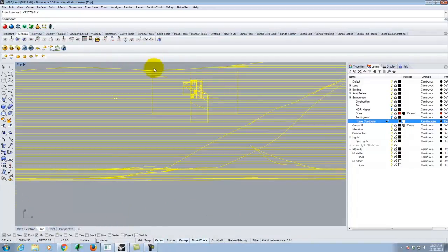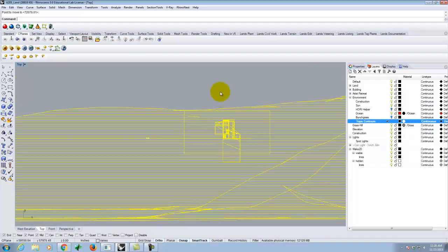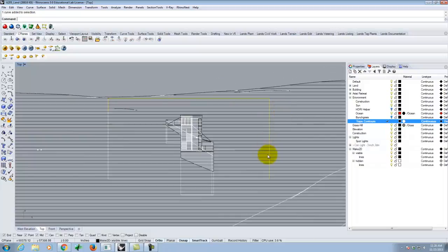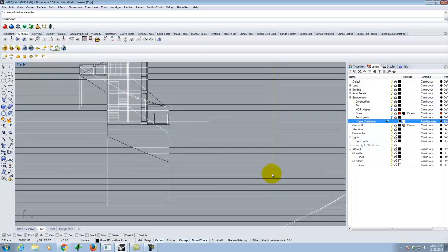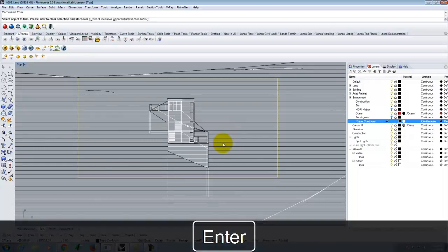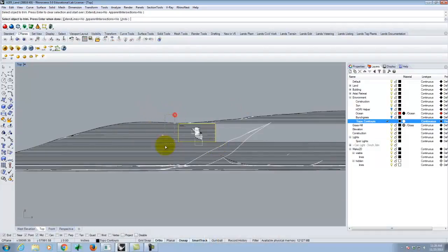And we see, this is what I made a mistake with last time, that this rectangle represents the view that I was just looking at. Okay? So I'm going to click off of this and clean it up. I'll use that viewport rectangle right here, take both sides of it there, and I'll use that as a trim. So I'm going to type trim, and I'm going to get rid of all of these lines that are outside of it.